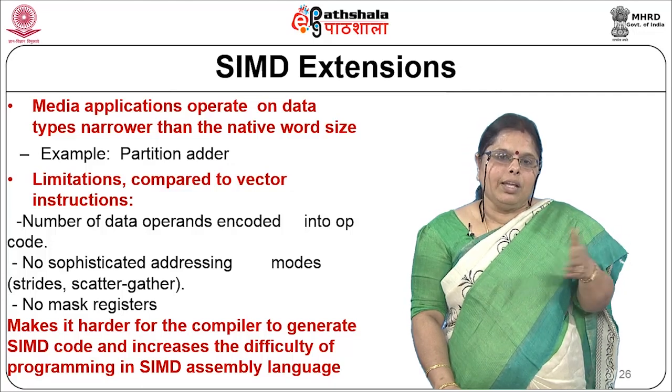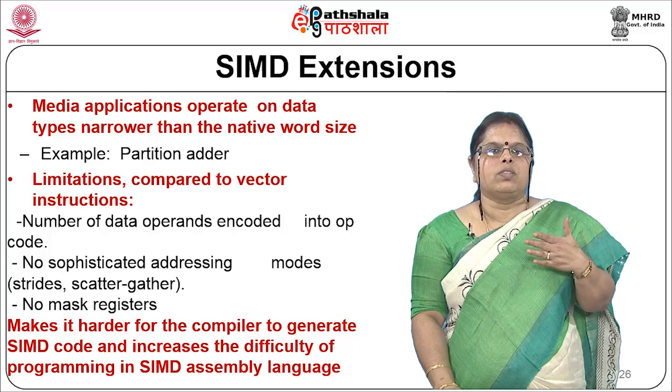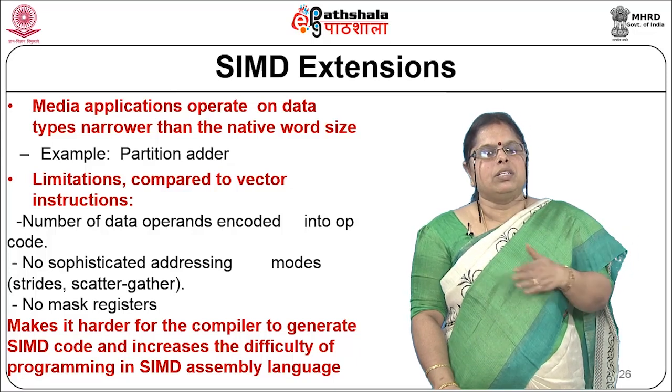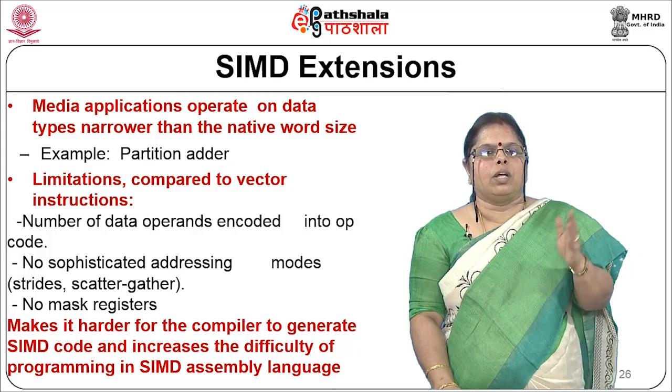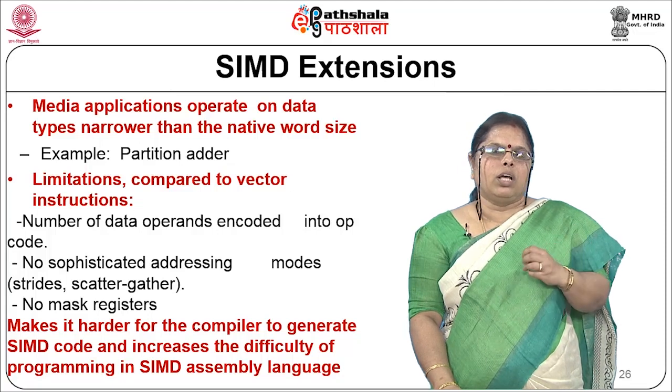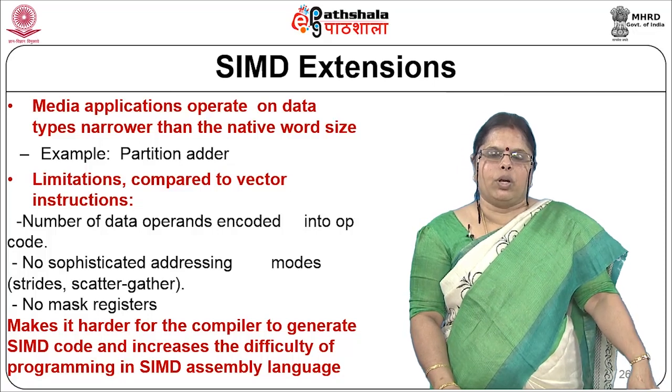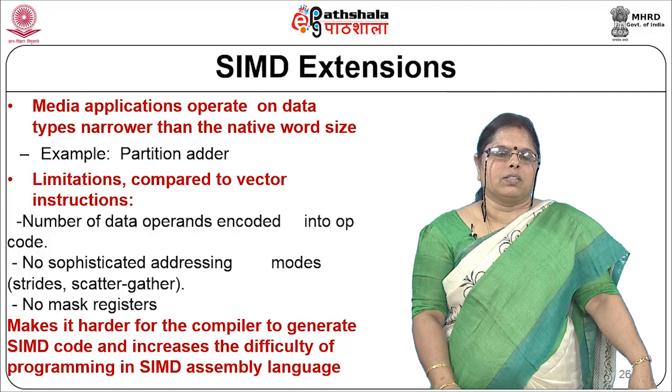Now, this can be easily done. You anyway have a 64-bit adder, just partition it into 8-bit adders or 16-bit adders or 32-bit adders. So, that is a very, very simple extension that you can do to the existing architectures.